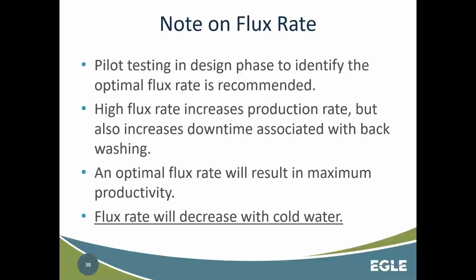I think it's GFD. I forget exactly, it's gallons something per day, but it's analogous to your filtration rate for conventional filters. But you can basically think of it as the flow rate per square foot or whatever of membrane material.